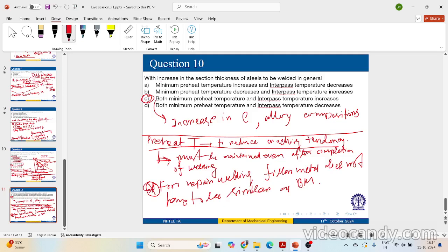Now I was talking about this weldment that must be stress relieved or tempered after welding. In some repair welding, where neither annealing or over tempering the steel before welding, nor stress relieving the weld upon completion is feasible, electrodes of austenitic stainless steel or nickel alloy steel can be used. So just remember that. I just made some note.